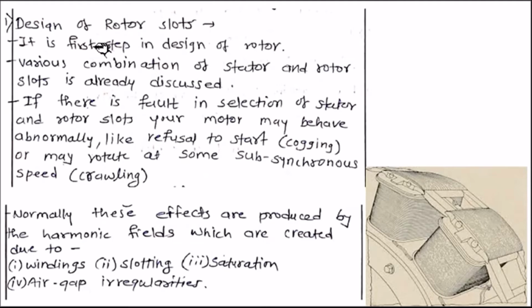The first one is design of rotor slots. Now this is the practical rotor having some slots. This is the first step in designing of rotor, and previously we have discussed some rules to design or to calculate stator and rotor slots. That is most important for selecting the rotor slots. And if there is a fault in selection of stator and rotor slots, your motor may behave abnormally.